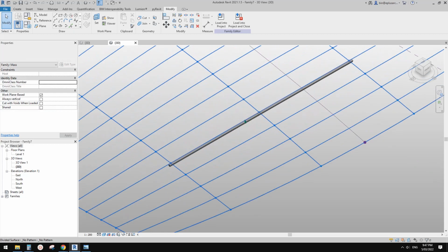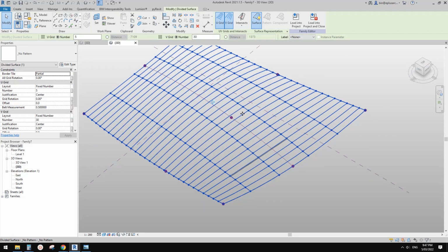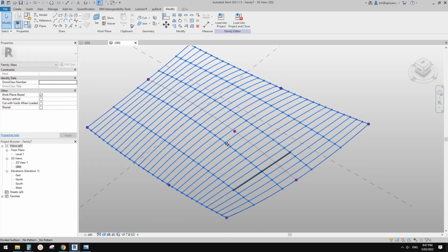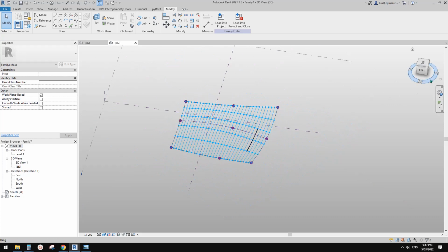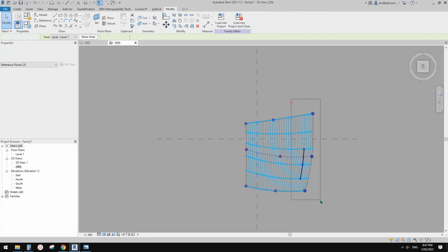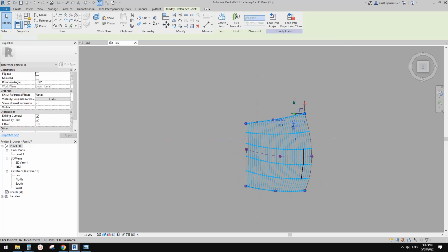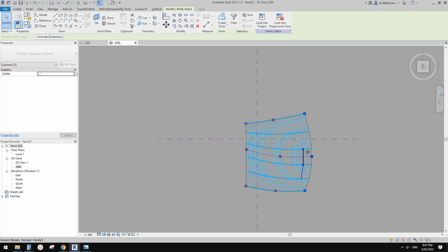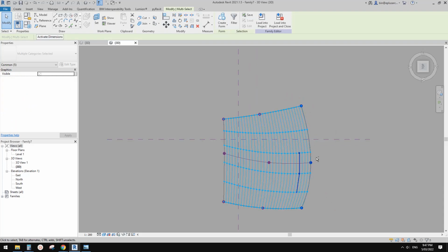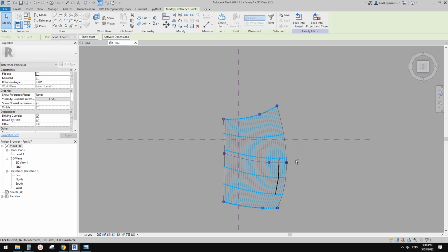Okay, so it looks very skinny, but this is because of the size of this massing. I'm going to actually reduce the size a little bit, and then you can just go select these points and use your keyboard to adjust these points. Oops, wrong direction. Okay, so you can select all the points, not this family. So maybe I'll use Control and select and just reduce the size of this mass.